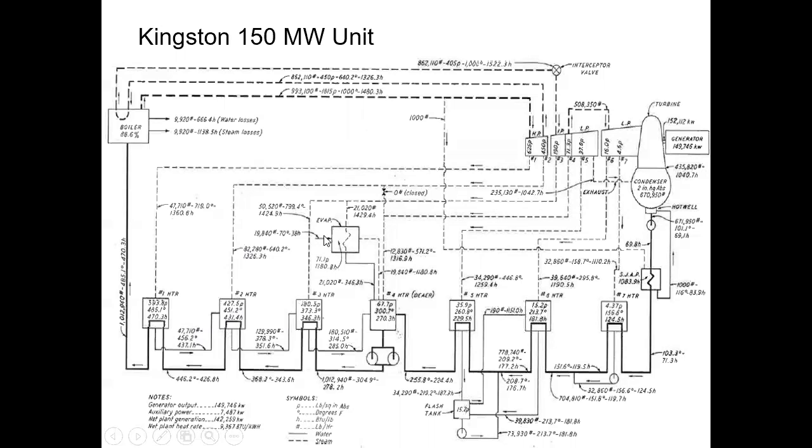And then whatever the amount of extraction steam, where is it? There's another 50,000 pounds an hour. So now I'm up to 180,000 pounds an hour of condensate. And then it gets dumped into the open heater, and that's where that condensate then comes back into the feed water, okay? And then on these, it gets trapped back. And on this one, we actually pump it.